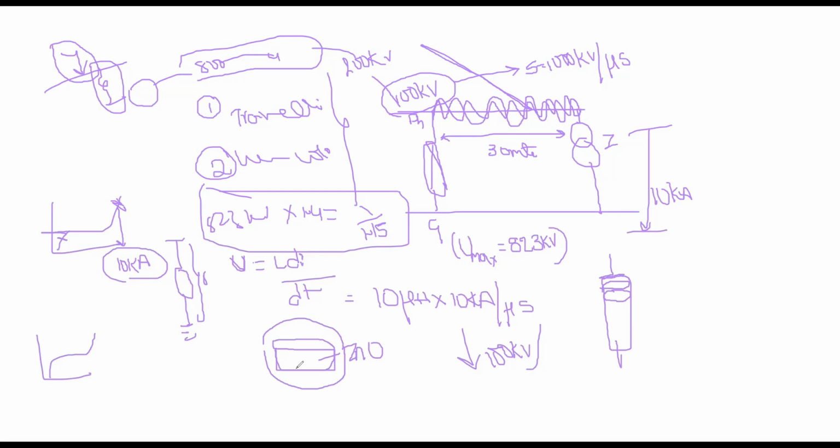Due to this temperature rise, excessive tensile and compressive forces will act on the metal oxide resistors, the ceramic, which will lead to cracks in the resistors. The resistivity property will fail, so the lightning arrestor will be damaged. ZnO blocks will fail. ZnO blocks are failing due to the temperature rise.